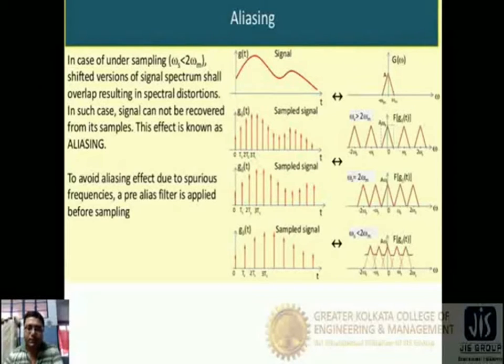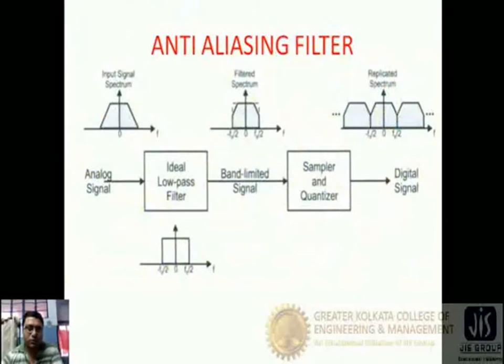So the solution is the anti-aliasing filter. Anti-aliasing filter is the solution. For that, an ideal low pass filter or band limited filter, which means it limits to a certain band and rejects the higher frequencies present in the signal.